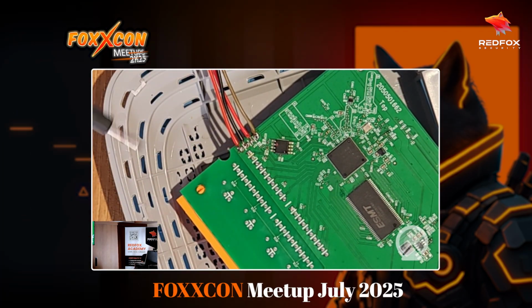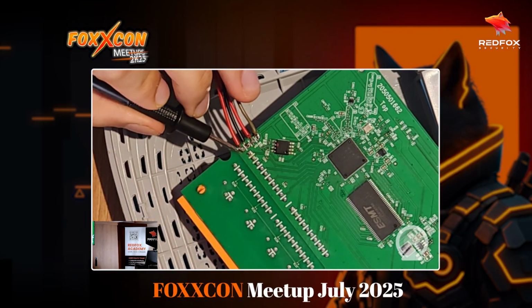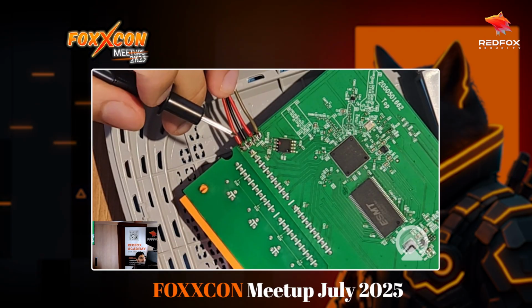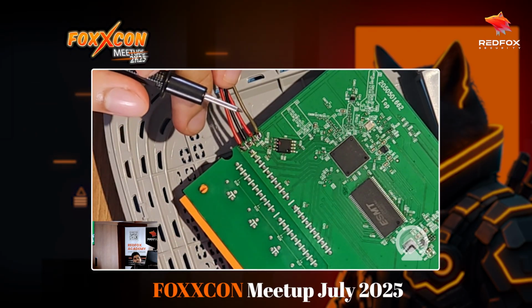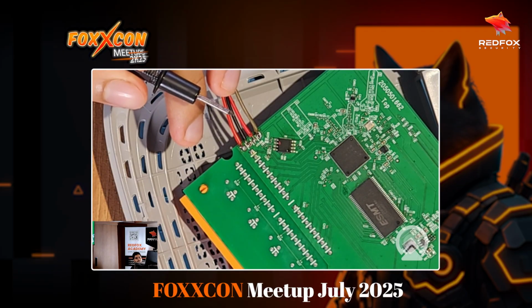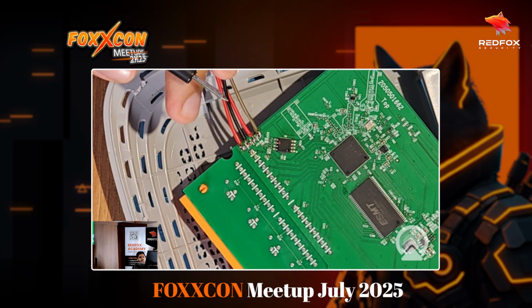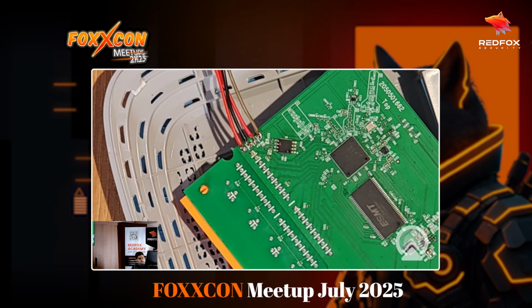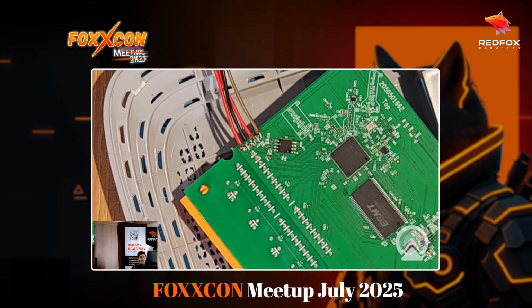Okay, so we have the first connector. First, what we do is we try to find ground. The reason for that is because if you have ground, you can figure out most other things as well. Like if you have ground, then you can figure out which is VCC, because if you put one end on the ground and one end on VCC, voltage will be transmitted. So you'll see that on the multimeter directly. So what we do firstly is find ground.